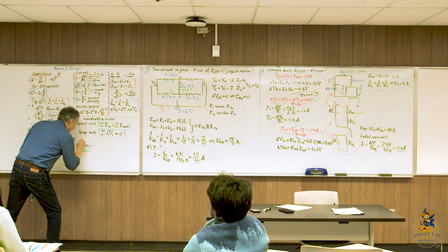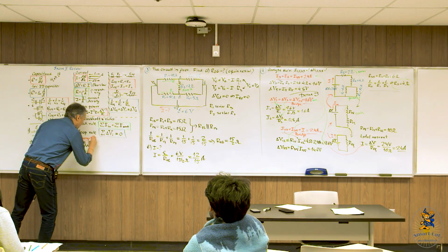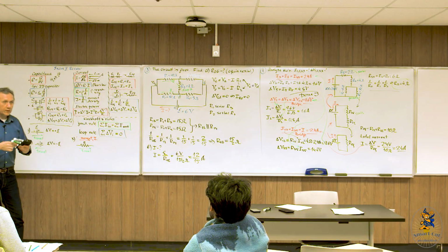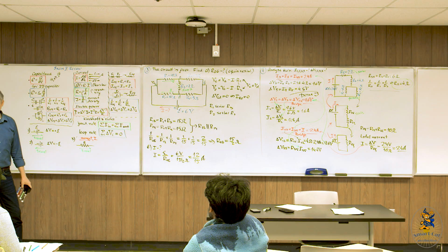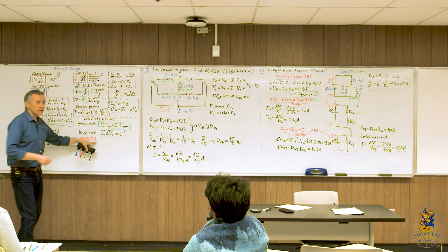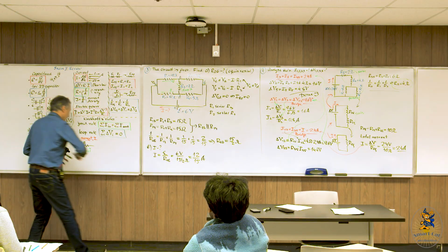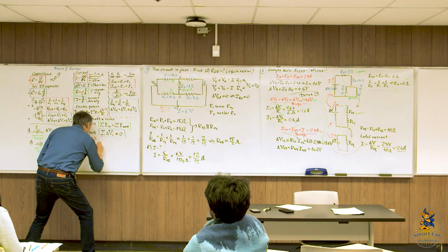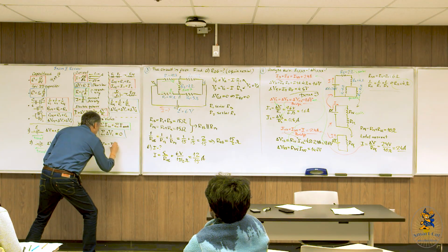Okay, let's assume that I picked this direction as our current direction, I. So now, mnemonic rule. If both directions are the same, is the contribution positive or negative, do you remember? Negative, minus IR. Right? Current is unknown, resistance is usually given, most of the time in the classical problems. So delta V is minus I times R.